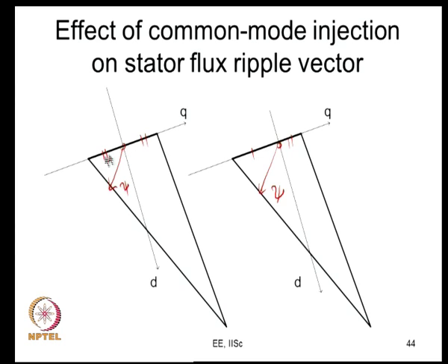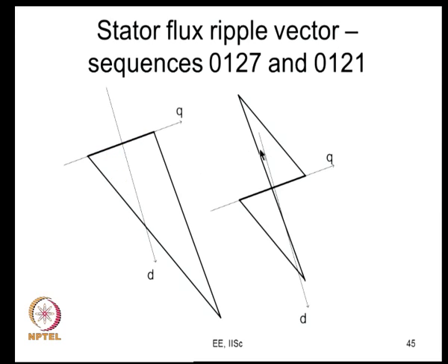If you divide that, what happens? The q axis current ripple reduces, therefore, the torque ripple reduces, of course, the overall current ripple also reduces now. So, this is one comparison. Conventional space vector PWM is better than sine triangle PWM and third harmonic injection except 1/4. Third harmonic injection 1/4 is similar to conventional space vector. So, it is better than those PWM methods now.